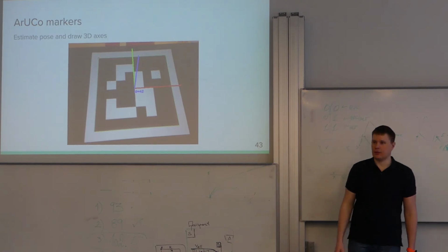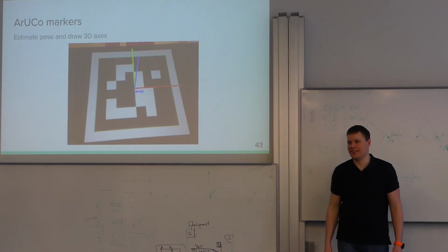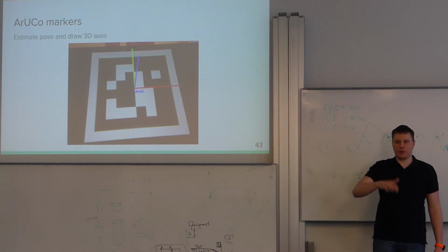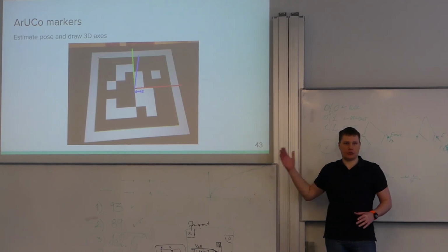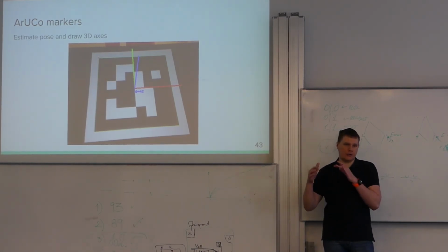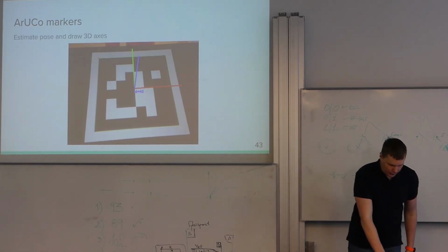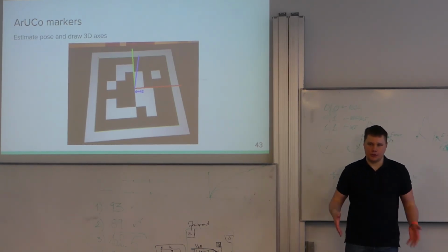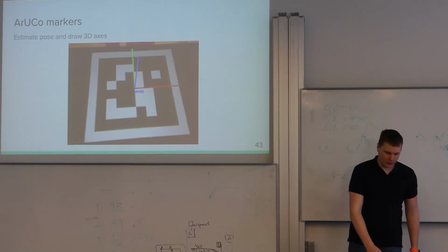So it means I can change my bolts to the ArUco marker? Yeah. Actually, if you want to have decent accuracy, it's better to use ArUco markers as your special objects. It gives you very, very good accuracy, and it's easy to detect. No false positives, so they are specially constructed, good objects.